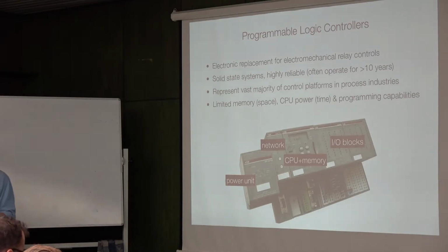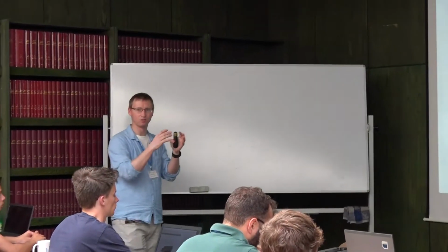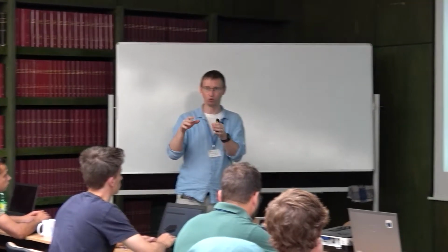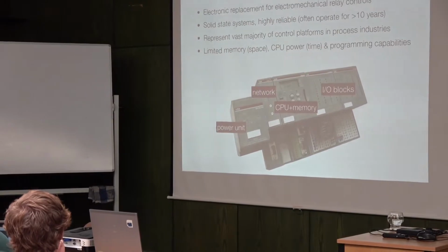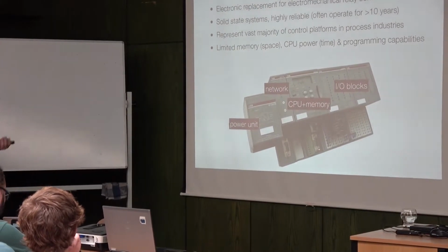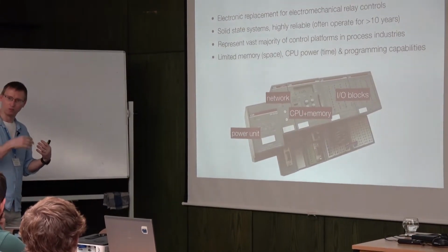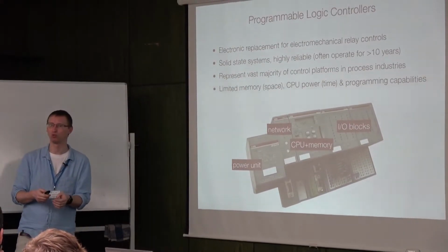Yeah? You previously said that this PLC is a bunch of logical units, right? Which are completely software-based nowadays. Okay, so the processor basically emulates these logical units. Precisely that, yeah, exactly that. So everything runs on the CPU. There is no hardware configuration. Unlike FPGAs, where you let the program basically synthesize your hardware board, here everything runs in a software fashion, but internally it works pretty much according to those logic rules.